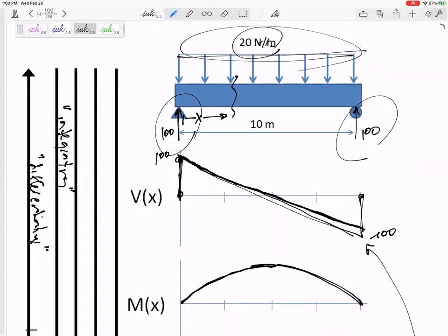So let's get back to these shear and moment diagrams. If we want to draw a diagram that tells the shear at every single point, that's our shear diagram. If we want to know the moment at any point along these simple beams, then we can draw our moment diagram. We could cut it at lots of different places and resolve some of the forces in y equals 0, some of the moments equal 0. But we're not going to want to do that.